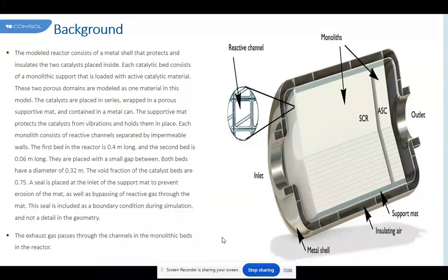Conversion efficiency is also affected by the cell density distribution of the substrate. This effect is highly correlated to the fluid distribution among the cases analyzed. It is found that a relatively small core inserted in a monolith with a lower viscous resistance increases the pressure drop and decreases conversion efficiency simultaneously. Hence, such a combination is highly discouraged. On the other hand, if the core has a low viscous resistance, then the pressure drop and conversion show a positive correlation.